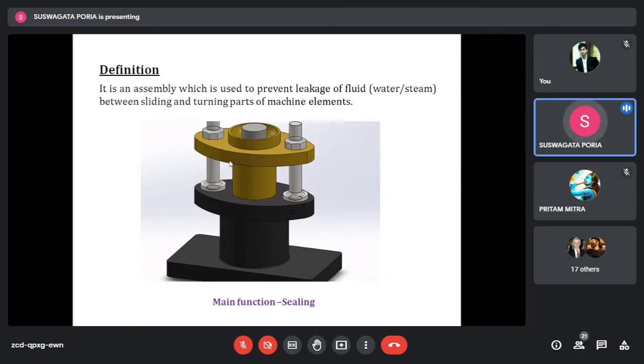Now, from basic concept, if you want to draw it, then you will get a top view, a front view and side view, and that is very simple. You can draw it from your first year knowledge. But I am telling you that when you draw it without cutting it, you will miss the major components, major features which are inside it. So for that purpose, this type of component we have to draw either by half section, by cutting a quarter of it, in that way.